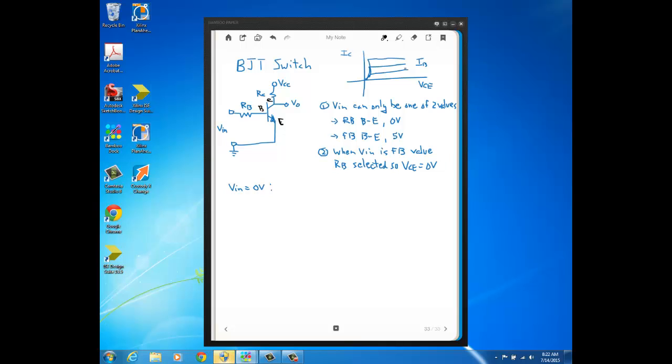Remember that these are constant base current curves, and we already talked about how when the BJT is used as an amplifier, we operate it in this region here that's called the active region, where beta is fairly constant, and also for all practical purposes the optimum beta.